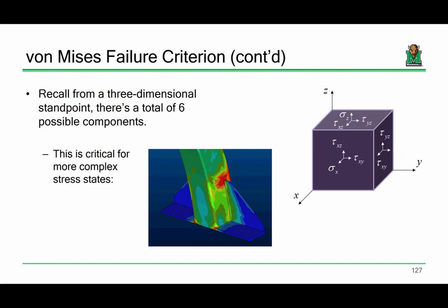So how do you determine if that stress state means failure for a given material? Well, it depends on the stresses, and it depends on the failure criterion you're using. So the Mohr-Coulomb criterion would not be appropriate for steel, because it is appropriate for more brittle materials.